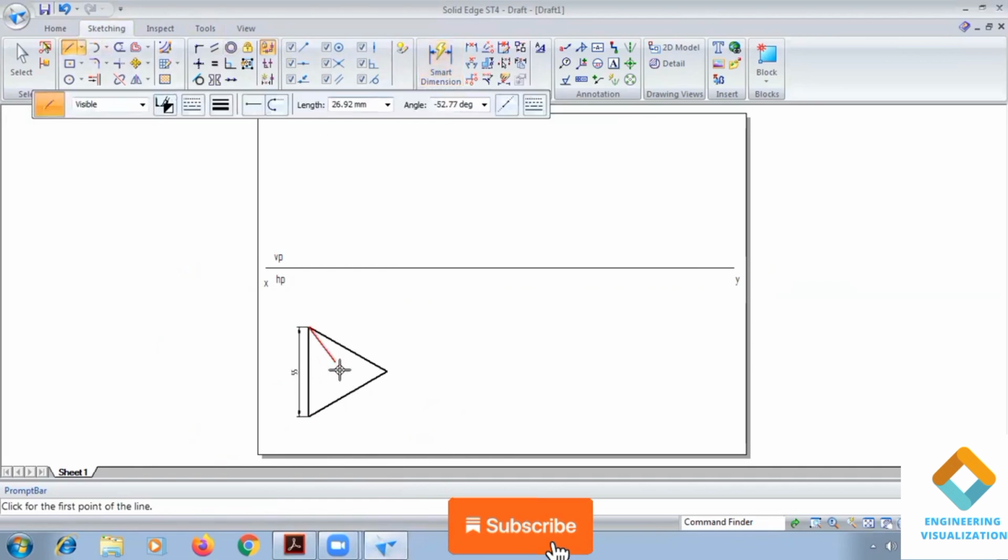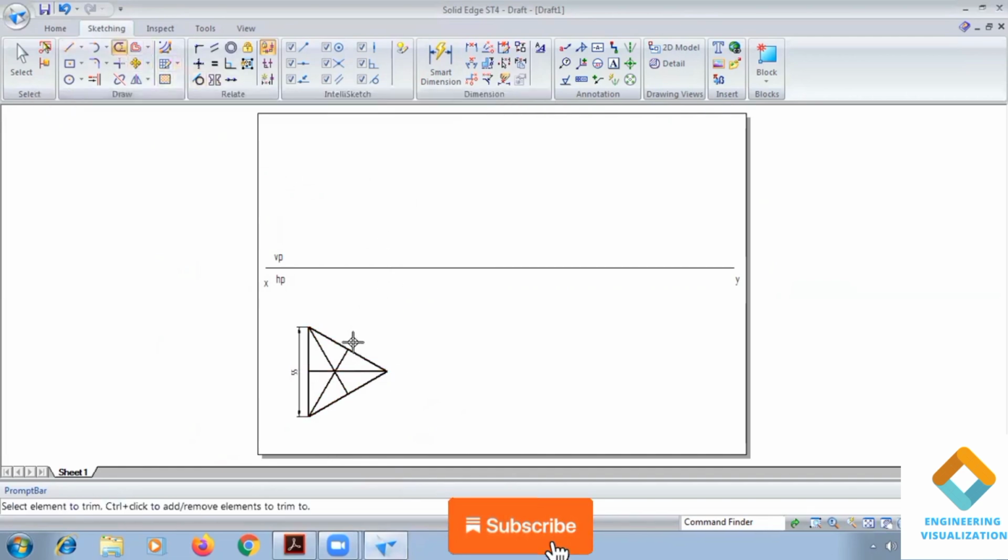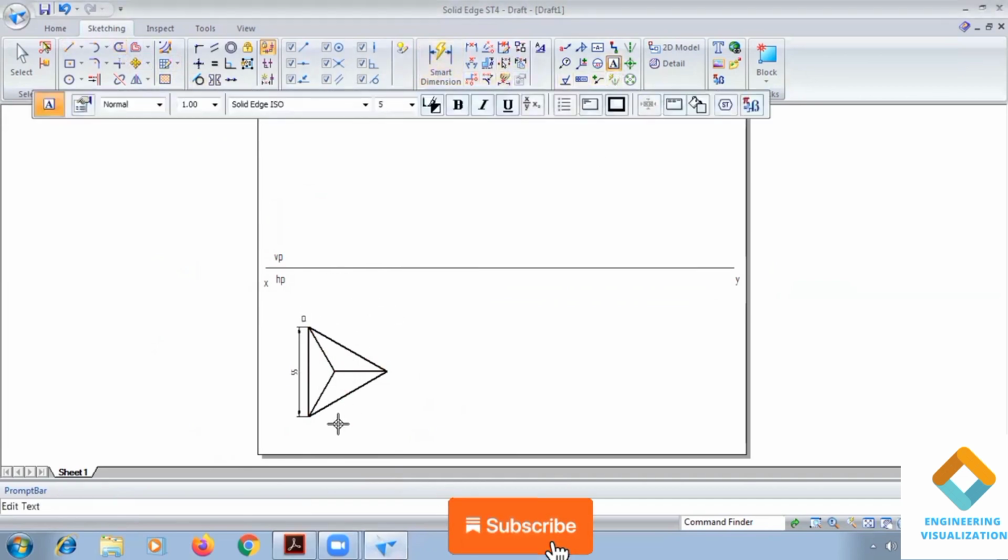Now draw the projection lines. Here we need to draw median lines. Two medians are enough to find the center, since it is a tetrahedron. It is one of the pyramids, so we need to draw all three slant edges. Now write the namings: A, B, C, O1.